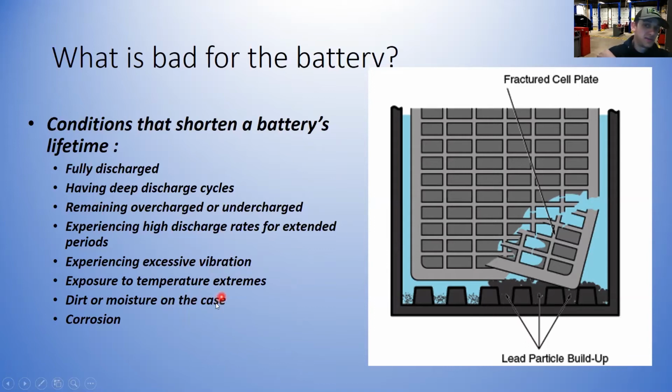Being exposed to extreme temperatures, whether that be extremely cold or extremely hot, dirt or moisture on the case, that creates a case drain, as we call it. It'll actually create a draw across that battery case, and of course corrosion.